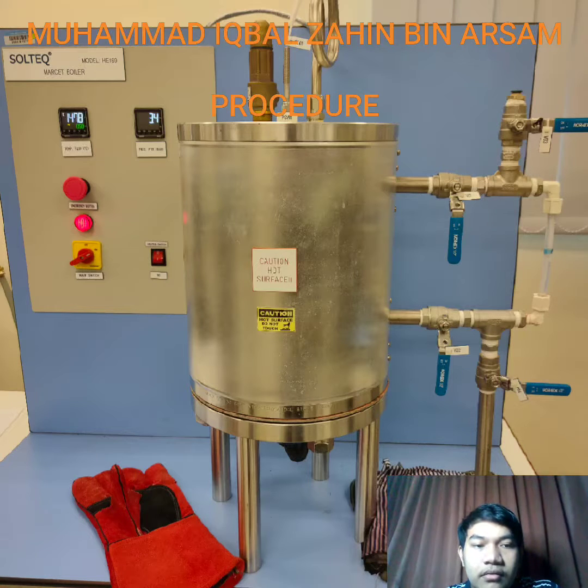Next, turn off the heater and the steam temperature and pressure will begin to drop. Start to record steam temperature when the boiler is cooled until the steam pressure reaches atmospheric pressure. Next, allow the boiler to cool down to room temperature. Last, record the steam temperature at different pressure readings when the boiler is heated and cooled.